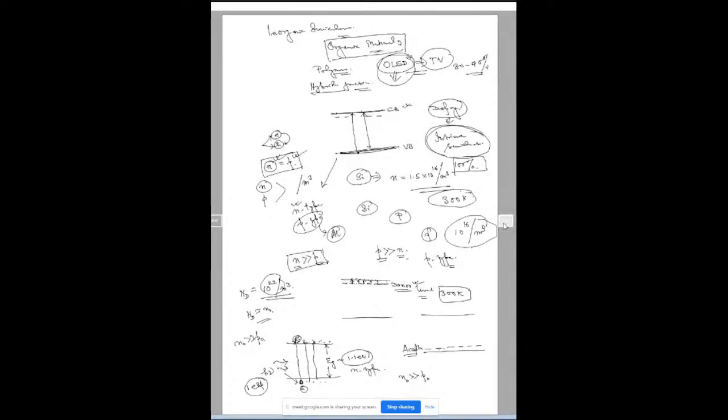Now, if I shine light, there will be some additional generation of carriers in the semiconductor, which will add up with the existing thermally generated carriers. So this is the interaction of light with the semiconductor, causing a change in the electrical characteristics, in the form of a changed number of carriers in the semiconductor in presence of light.